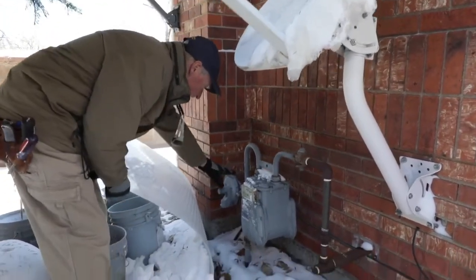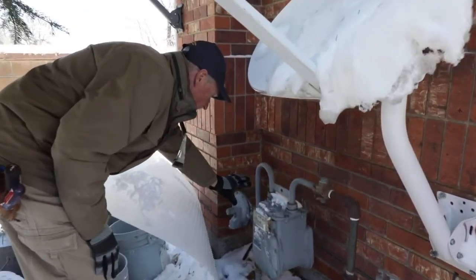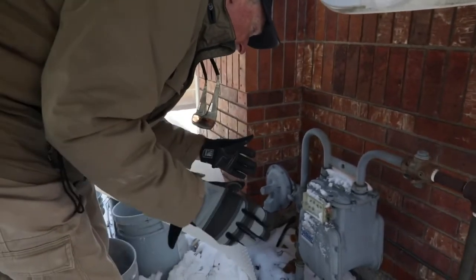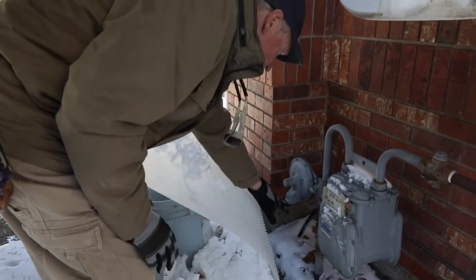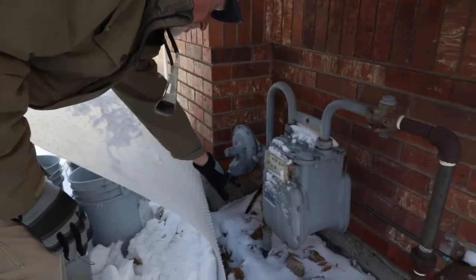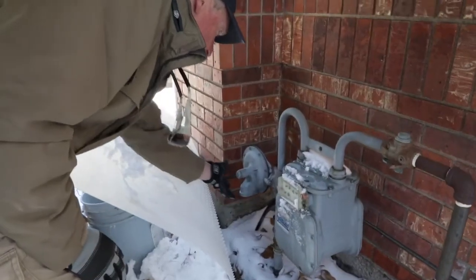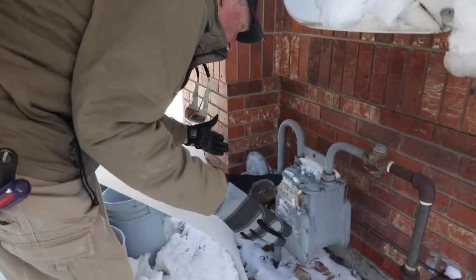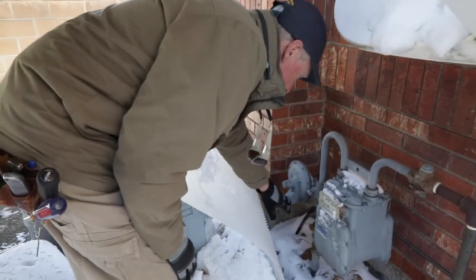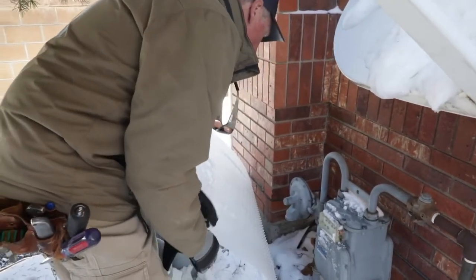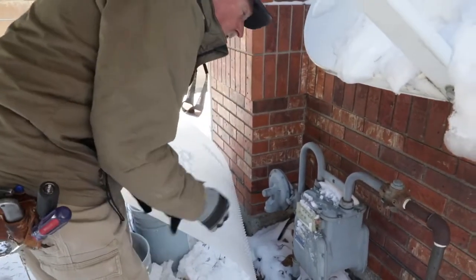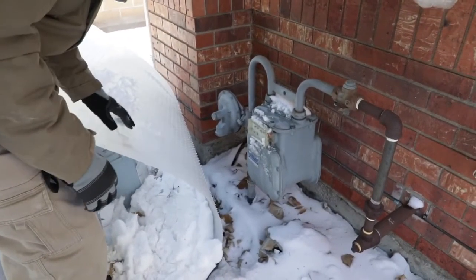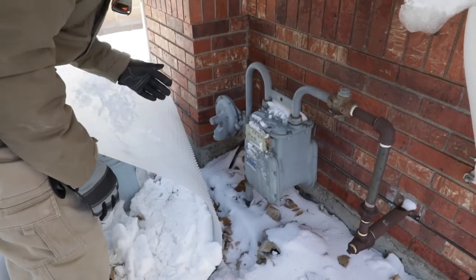Because this is a pressure relief system here, if there's a surge in the gas pressure to the house, it'll discharge that surge through the bottom of the relief here. So sometimes we have the good fortune, if you will, of being here just as it's releasing a little bit of overpressure out the vent here. So I'll let it do that, come back and check it with my gas detector.